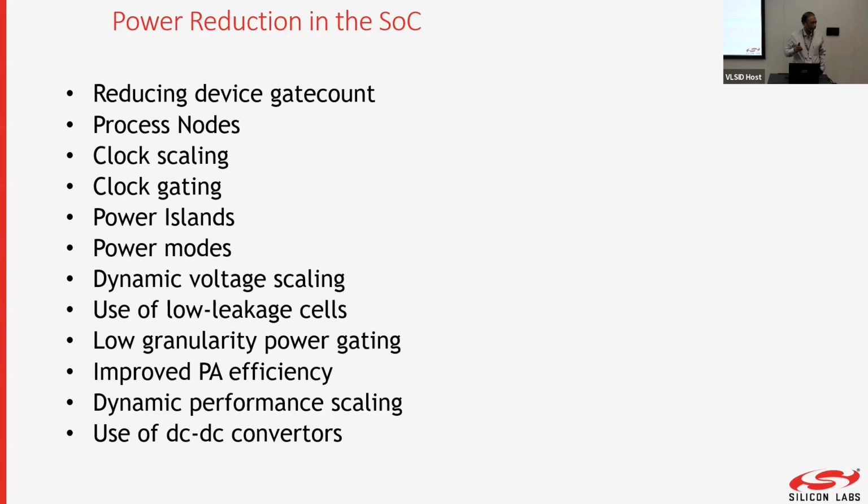They both conduct. Okay. And so the higher the clock frequency, the more the frequency of these instances where current is consumed. And higher clock frequency also means that you're charging and discharging capacitors more often. So reducing the clock speed to no more than what you actually need is important for conserving power. And that's called clock scaling.